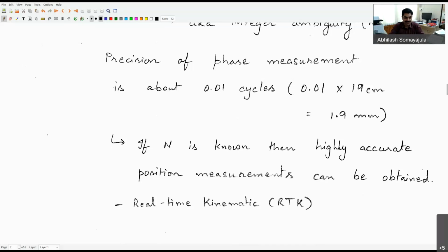Now, one of the main challenges with this carrier-based phase detection is that you do not know how many cycles of phase there are. So you can be off by 5 degrees, or you could be off by 365 degrees, or you could be off by 725 degrees. They'll all read the same phase difference, right? So the number of cycles by which you're off is something you need to know, and that's a sensor specific thing. If you know that precisely, then you can try to estimate it based on carrier phase difference based methods.